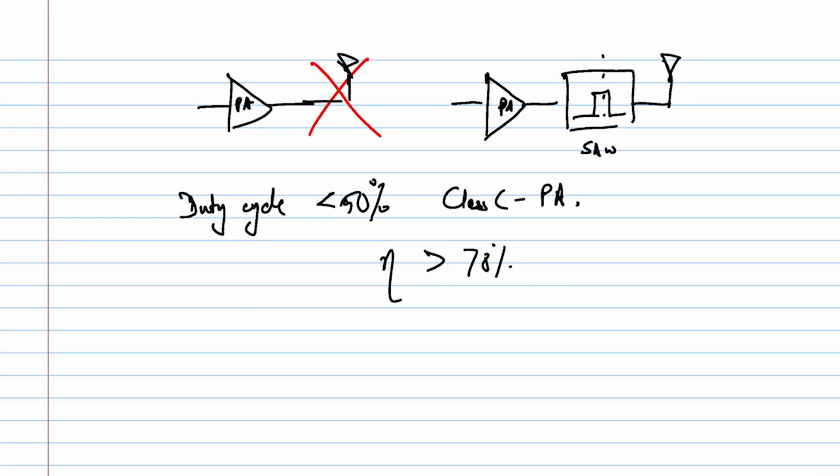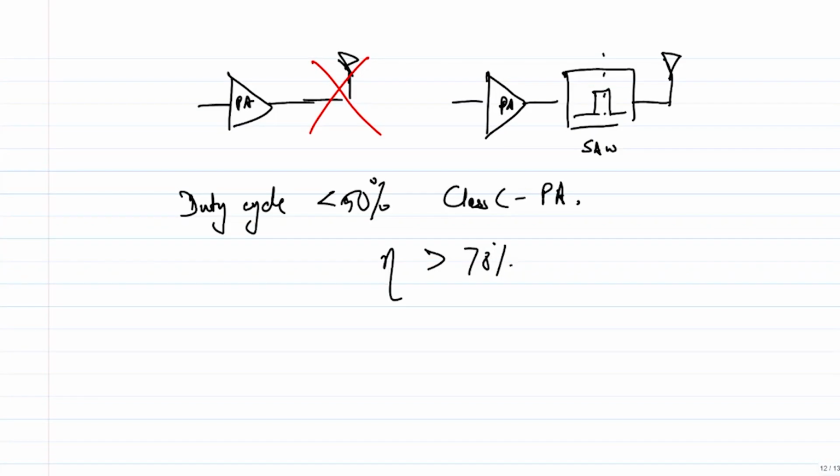If you do this, you are going to see obviously an increase in efficiency, and you can go crazy, but the issue again will be you will have more and more distortion. Which means that the filter you are going to need at the output of the PA will be bigger, probably require higher order roll off, and so on and so forth, right? Okay, fine. So let's stop here. We'll see you in the next class.